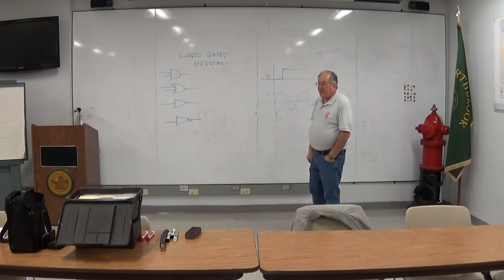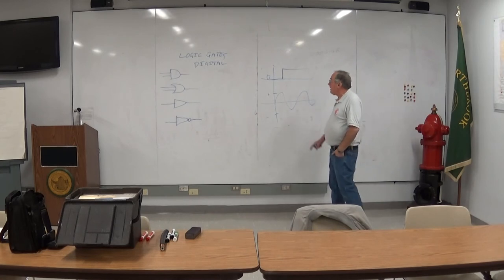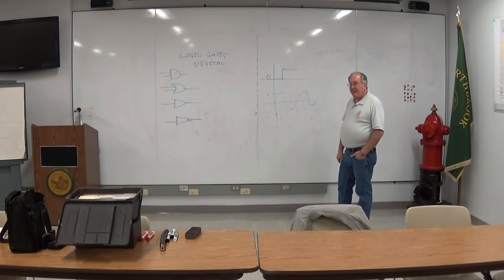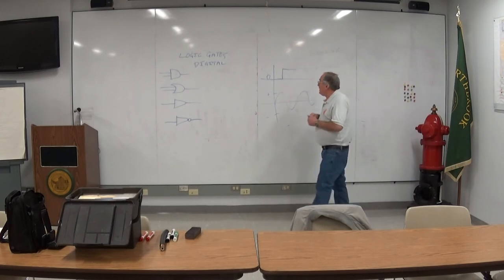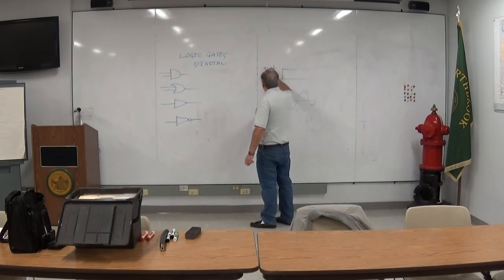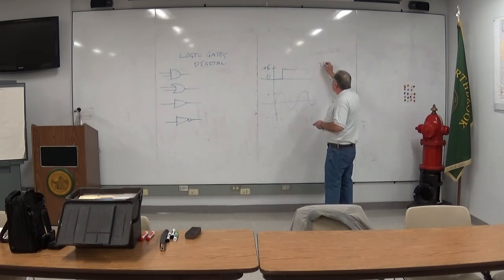Those were control lines attached to the other pins, depending on whether you had a DB9 or DB25 connector. Point is, it was all digital. You had 2 levels, whether it was minus 12, plus 12, or in most logic circuits, plus 5 seems to be popular, and 0. That's the so-called TTL levels.